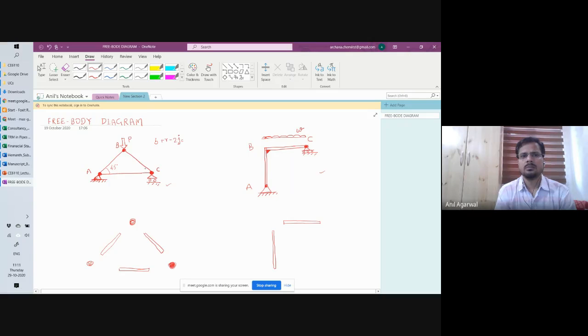Okay. So if you look at each joint, you have two equations. Each joint provides you two equations. And how many unknowns do you have? For each bar, you have one force, so that is one unknown, and each reaction is one unknown. So the total number of unknowns is b plus r, and 2j represents the number of equations, because each joint gives you two equilibrium equations. This is a plane truss, so there will be one equilibrium equation in this direction, another one in this direction. So this will be the total indeterminacy value.